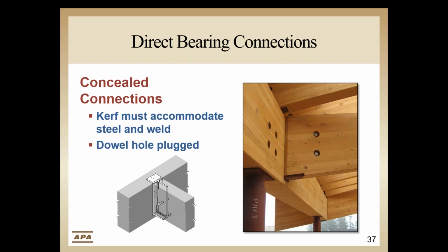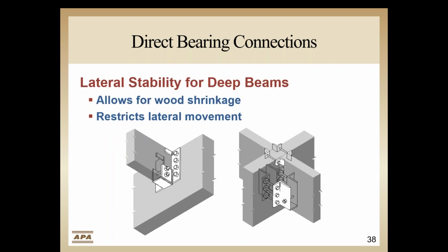Note that the kerf in the suspended beam must accommodate not only the width of the steel plate, but also the increased width of the fillet weld. This is also an insulating detail that is applicable in heavy timber fire-resistant design. Burying the metal underneath the insulated layer of wood prevents the metal from overheating into a plastic state during a fire event. See American Wood Council's technical report, Calculating the Fire Resistance of Exposed Wood Members, TR10, for additional details. This document is a free download on the American Wood Council's webpage.